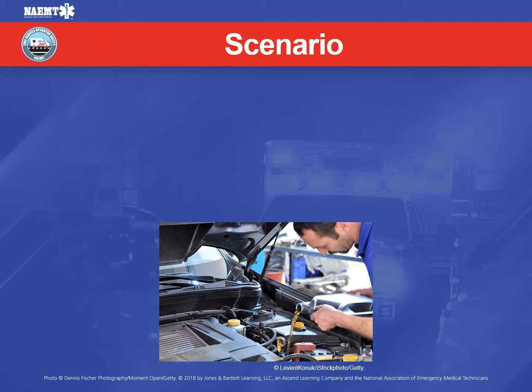The supervisor explained the color is an important clue to determine what type of fluid is leaking. For example, motor oil is typically golden to black in color. Antifreeze is typically green and watery. And the transmission fluid is red with an oil-like consistency.